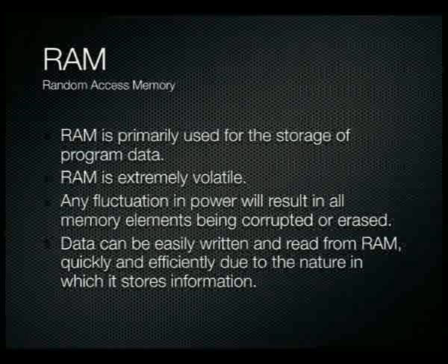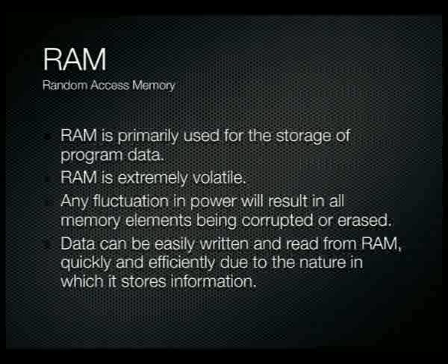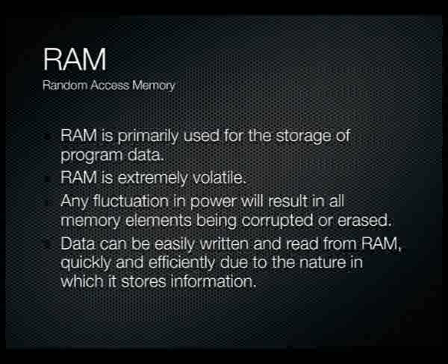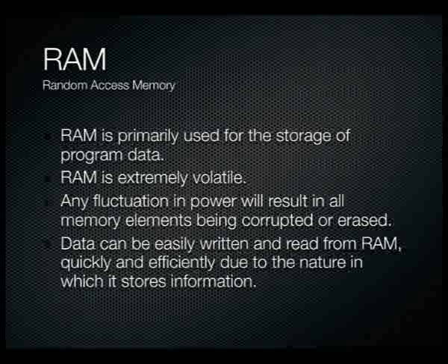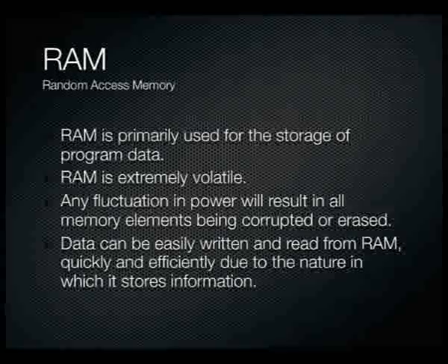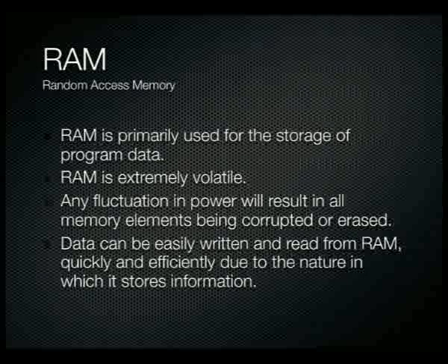The other type of memory that we have is our RAM, which is random access memory. It's kind of a screwy name for it, but this is the historical name, because memory is not random access anymore. It's not randomly reading from the memory; you can read anywhere, and you can read sequential memory locations. So it's no longer random access memory, but historically it's the name we use to define read-write memory.